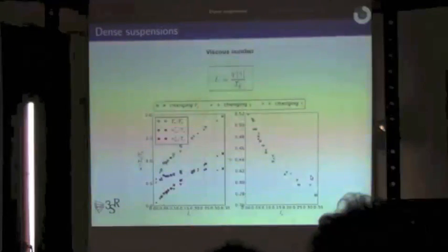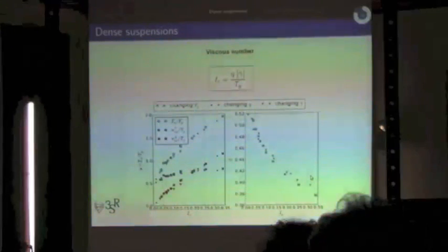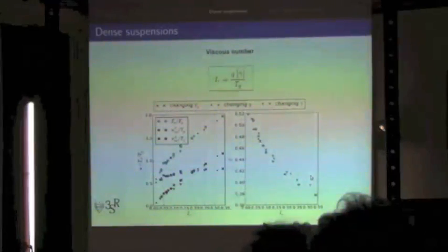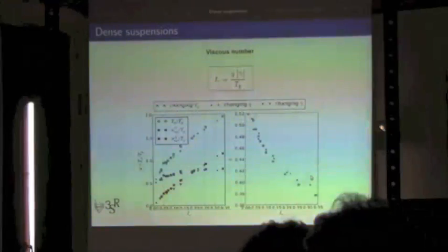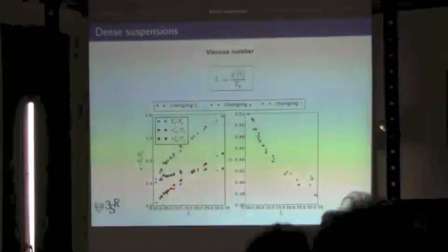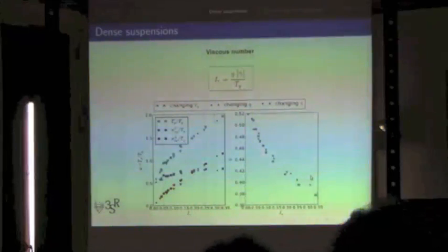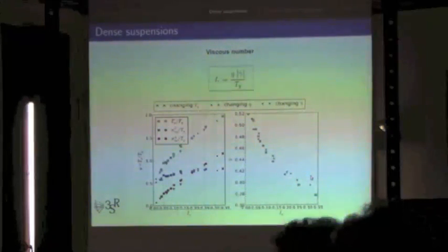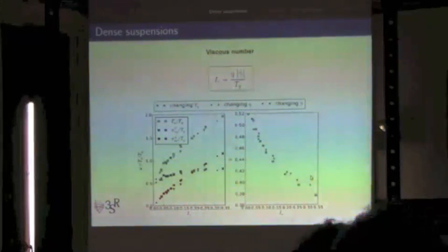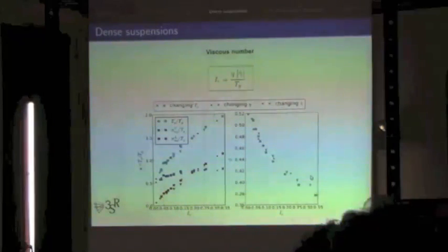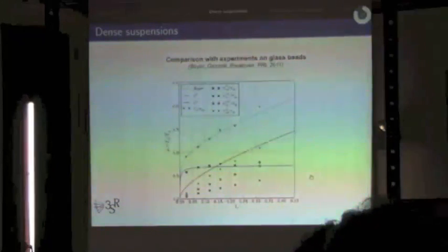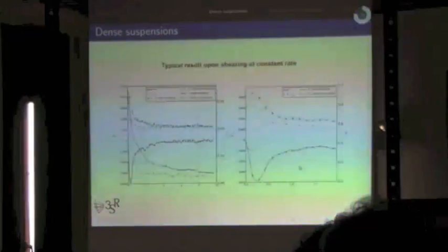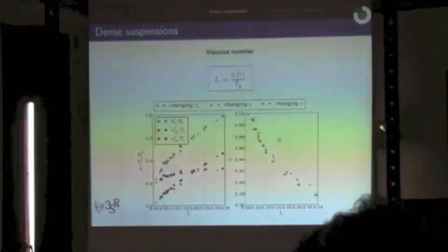But it becomes more fun if you plot the porosity, or here in fact the solid fraction, 1 minus porosity. You find that at the critical state, or steady state, porosity depends on the shear rate. So you have a critical state theory depending on the shear rate. This is the kind of funny effect that you have when you do that.